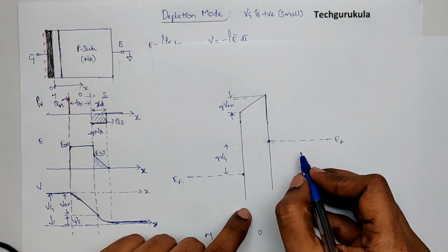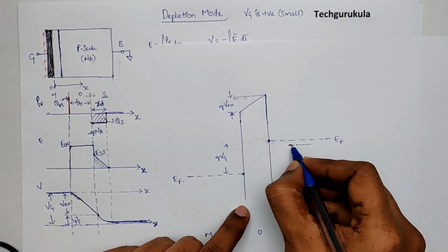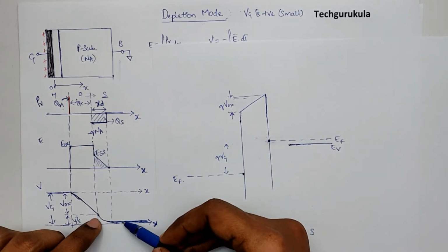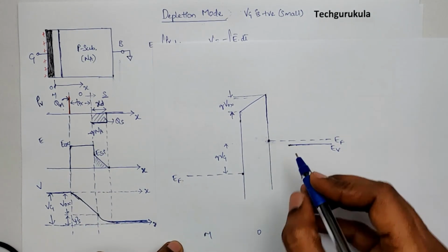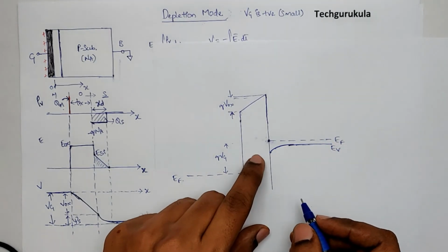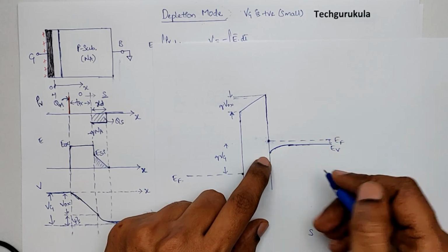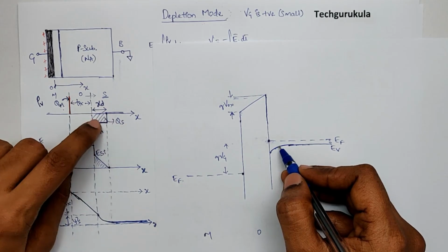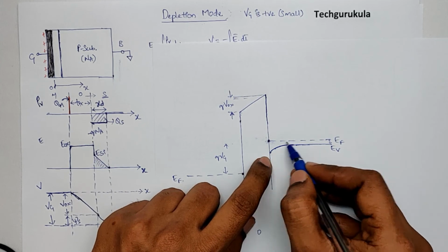So if we look deep inside the semiconductor, this is P type, so there will be EV here. Now as we know, here the bend is upwards, which means in electron energy it should be bending downwards. So I'll be drawing it bending downwards. Let's see if it makes sense or not. The hole concentration would be higher here because EF and EV are very close by. The hole concentration would reduce here. That's exactly the point we're talking about: this positive charge would repel the holes near the surface. Hence, they go away. As a result, the band bends downwards.